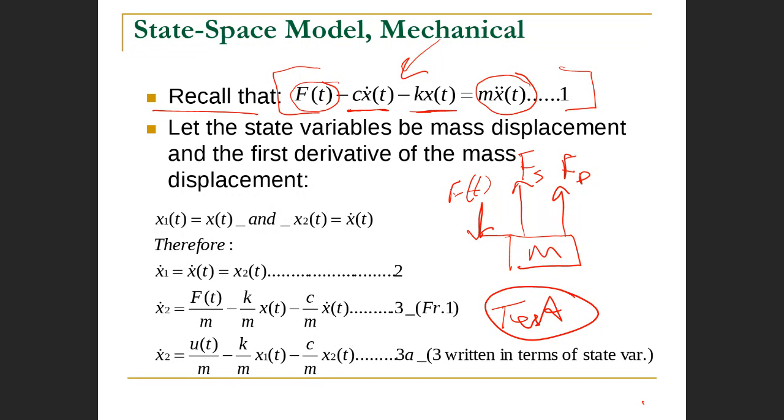So in this case, can somebody tell me what is the order of the system? Second order. And why is that so? Because you can see the two dots over the x. So the highest derivative term in the expression is double dot, which is the second derivative, and that would in fact be correct. Thank you. So it's a second order system.